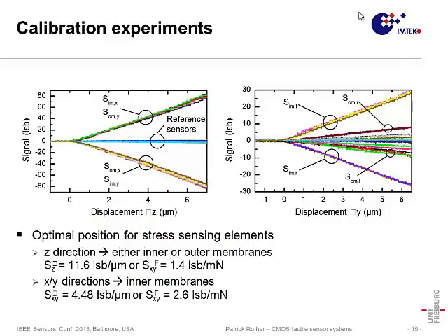Now, using these systems, of course, we had to calibrate them, and we had to look at the sensitivity of these systems. So we applied, okay, and this should be a delta Z here. At least this was on my computer. So we applied displacements of the probing sphere up to 6 micrometers in the same direction, in the Y direction. We monitored the signal of our AD converter. So what you see here is the least significant bits that is obtained from the system itself.